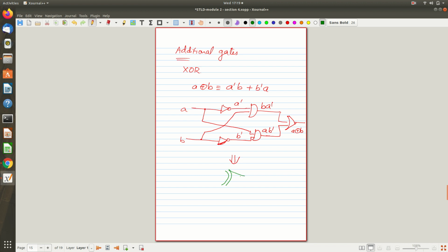This is a typical notation. It is like the OR gate, only we use one more symbol like this, so you can remember. This is the notation we typically use. So with inputs A and B, the output is A XOR B, so you are getting it directly. For example, if I give A as 0 and B as 1, the XOR operation gives you 0 XOR 1 is 1, right? So you don't have to worry about what happened inside the circuit. Like that, we have ready-made chips also, but again they can be implemented using the AND, OR and NOT gates, as they are the fundamental gates.